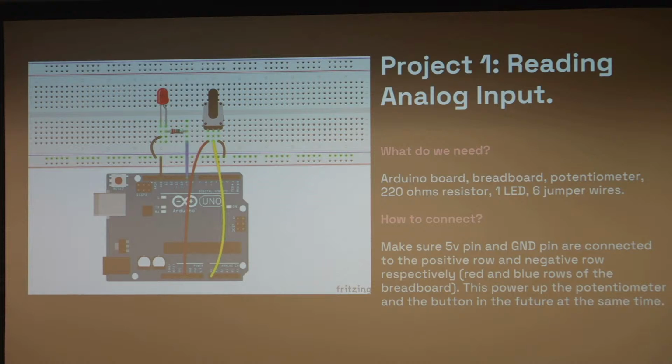Also, quick question. This one is not connecting. You might shrink the legs a little bit or move it so that it can fit. Or what you can do, because of how the energy flows in the breadboard, the little white thing: the energy flows column-wise.